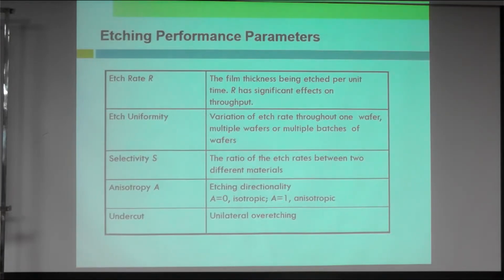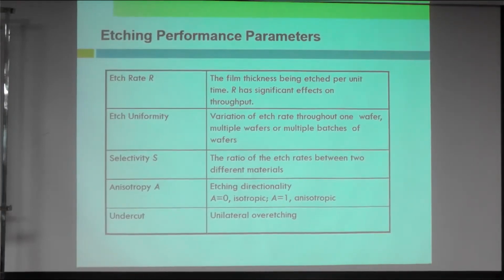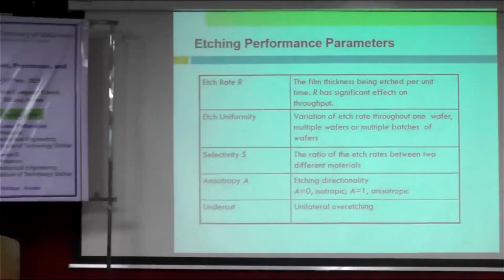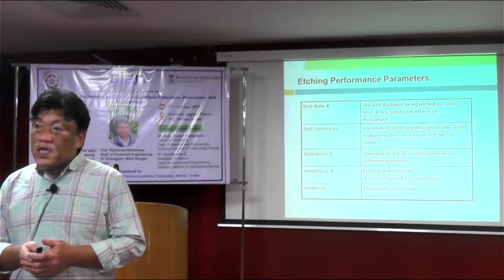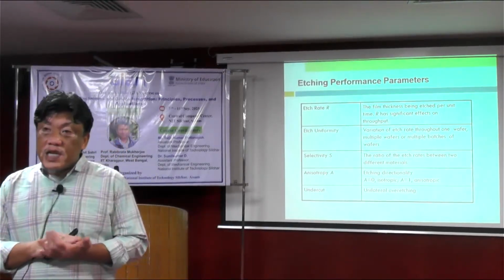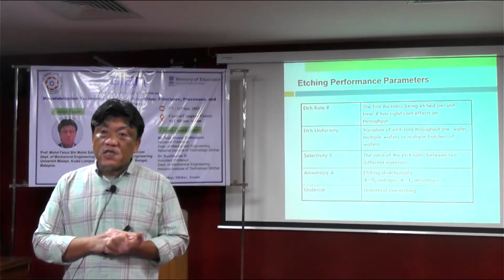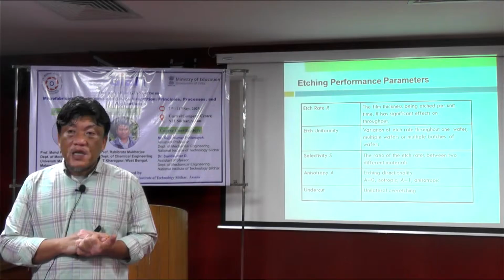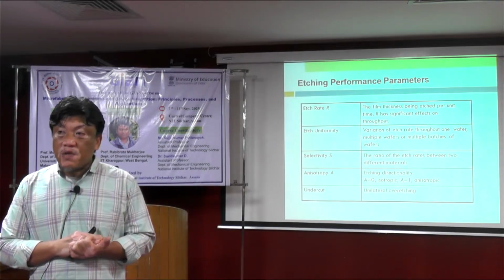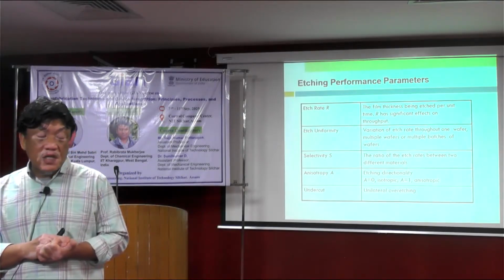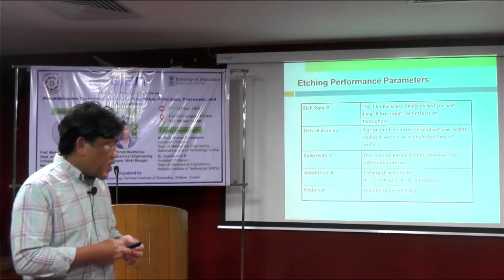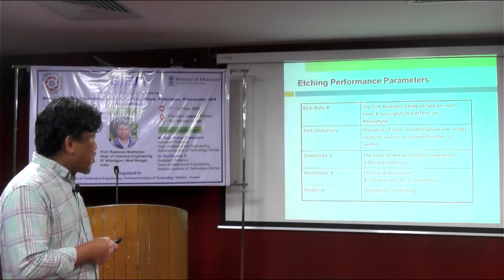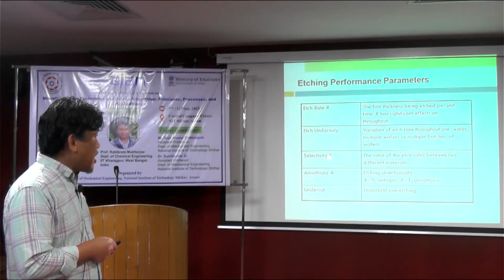You may want to remove, for example in a silicon wafer, up to a few micrometers, maybe 15 micrometers, or even 80 or 100 micrometers, while the polymer mask on top is maybe only a few microns, maybe 10 microns. So that will have to be considered.